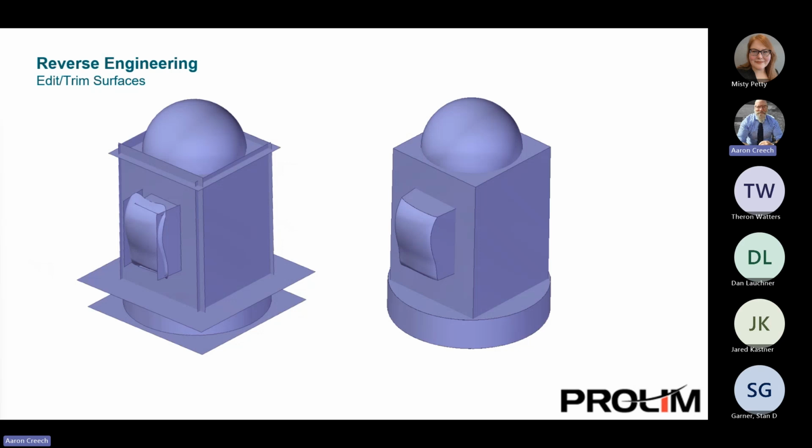This eases the trimming process and verifies and solidifies that you have a nice seam at the corners where these two surfaces may meet. On the right-hand side, we spent a few minutes clipping away and trimming and extending all these surfaces. And now we've got our desired result, but it's still just a collection of sheet surfaces.